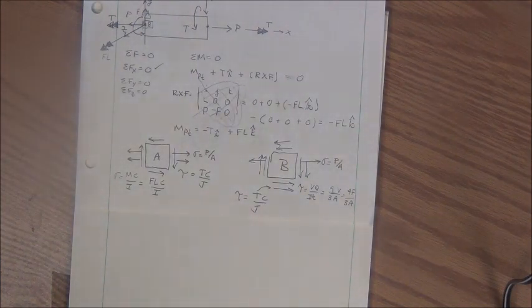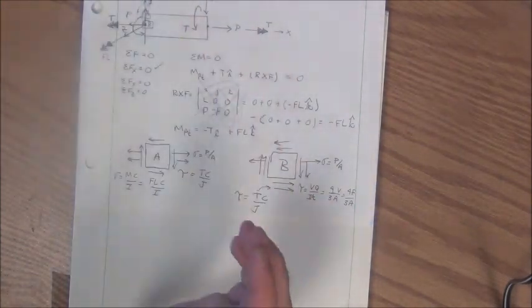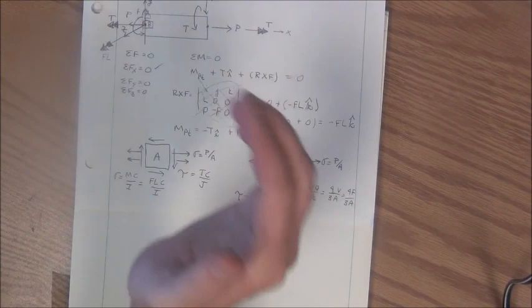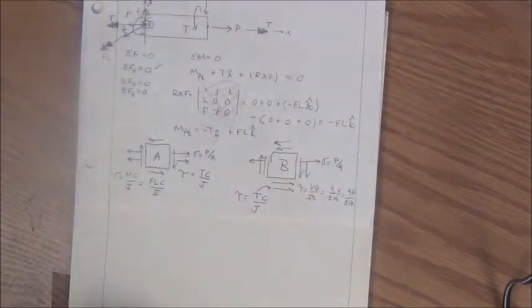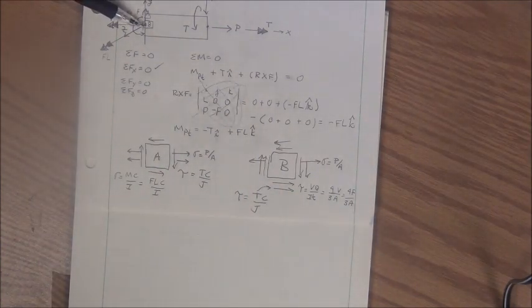The last load component to look at is this bending moment, and we realize that this bending moment is trying to bend my beam up, and B occurs at the centroid of that, and so it occurs at the neutral axis, and this bending moment FL will not cause any stress due to bending at location B because it's at the neutral axis.